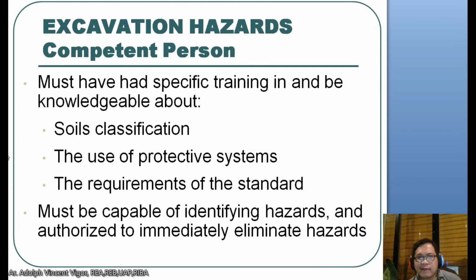For excavation hazards, a competent person must have specific training in and be knowledgeable about soil classification, the use of protective systems, and the requirements of the standards, and must be capable of identifying hazards and authorized to immediately eliminate hazards.